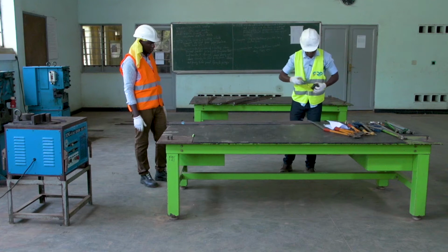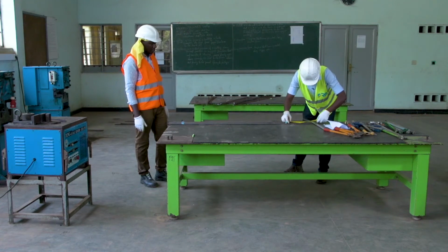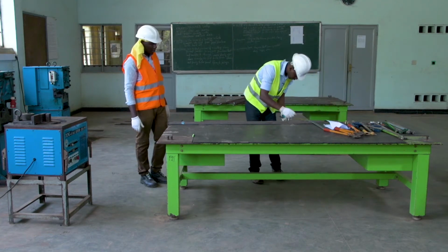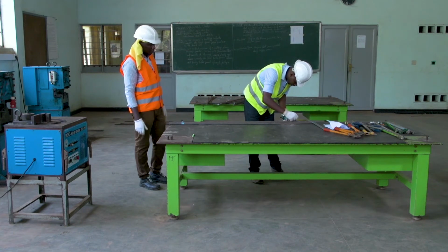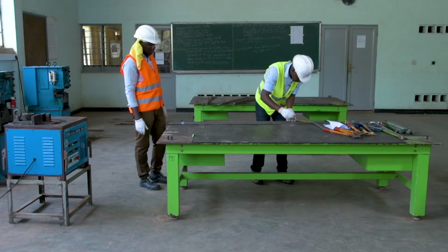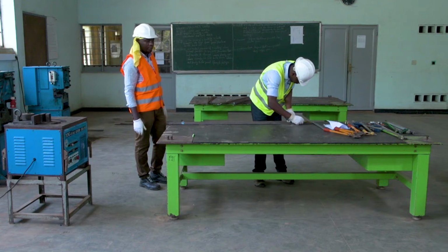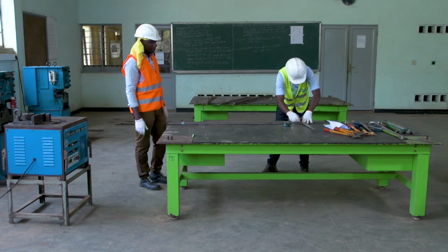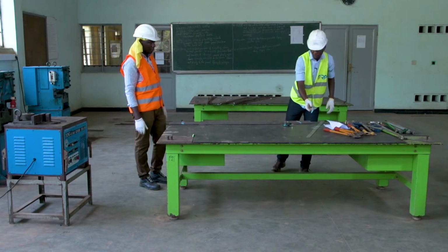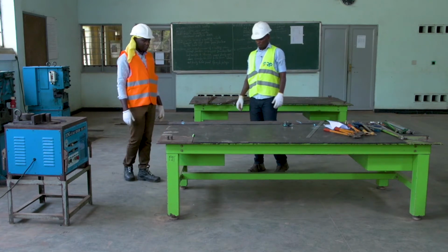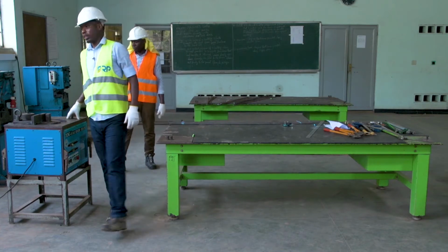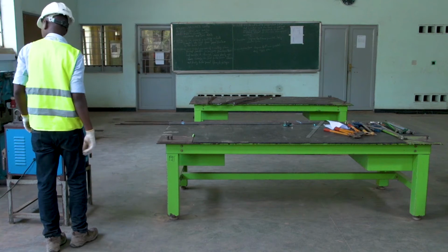Remember, our bend is 15 centimeters according to our drawing. Here you have 15, and this one we are going to mark 15 for a bend. Then the marking for the main bar of a footing is finished. Now we are going to start to bend these main bars.